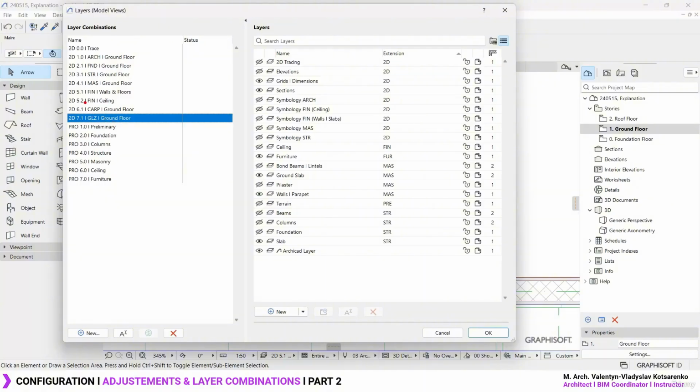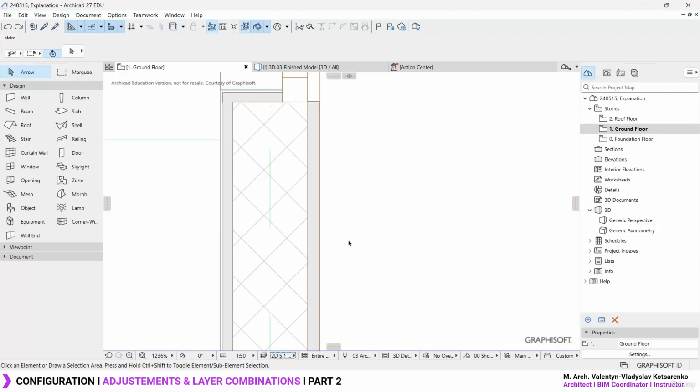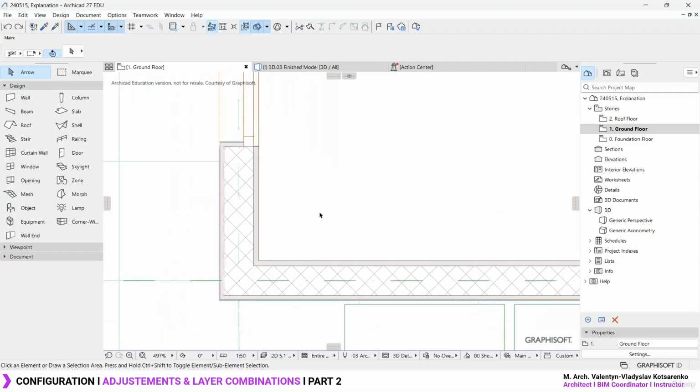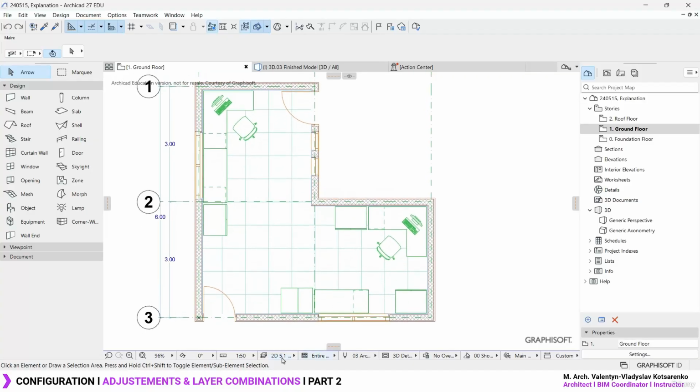Now for carpentry and glazing you will notice that we don't have a symbology, but if you want to add a layer for the symbology, go ahead. In a real project you will most likely have a layer for the symbology. For this example I'm not going to mess around with extra symbology, but I leave the decision up to you. Let's hit the OK button. So as you can see, it's pretty much fixed for the finishes, and it's displaying quite decently.